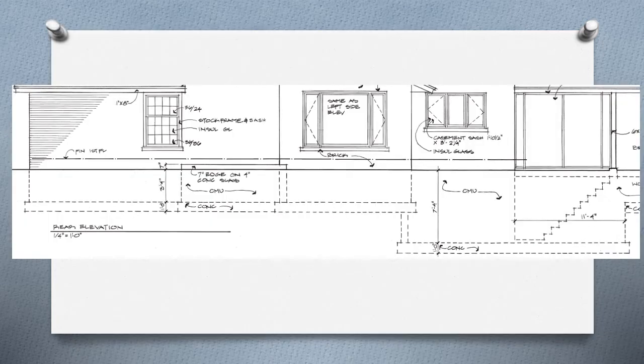Now, looking at the rear view, we can see that the basement footer ends 7 feet 4 inches below ground with another 1 foot, so the base of the footer will be 8 feet 4 inches. Here's my concrete masonry units, and notice the wall is concrete masonry units, the footers are concrete. And concrete masonry units, by the way, is just another term for cinder block.